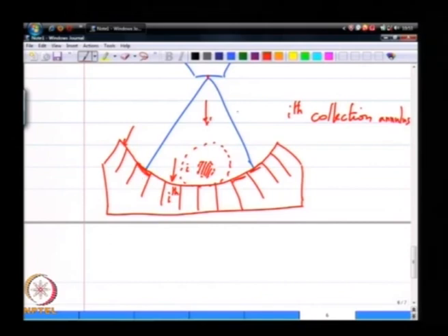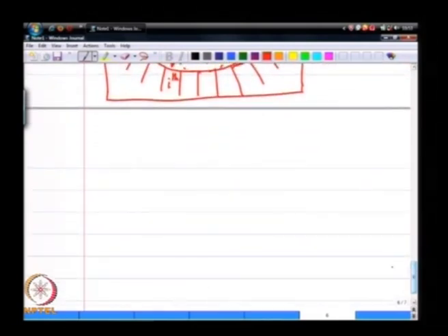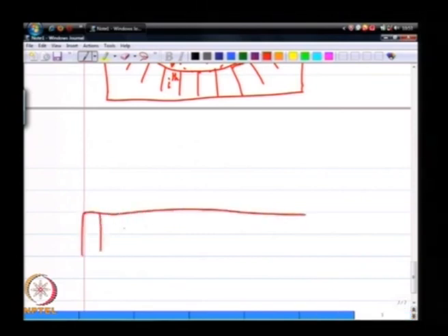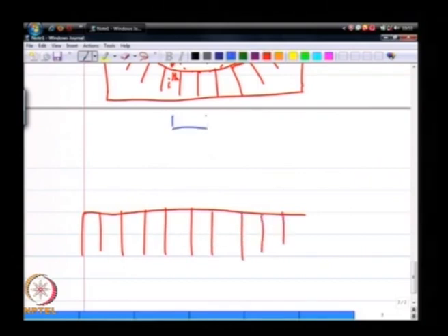So, in an inline design, the v dot dA, the angle between the velocity vector and the area vector are different, and that causes, even though I am thinking that I am exposing the liquid to the same cross sectional area, the cross sectional area that the flow actually sees is different depending on how far out away from the center line that particular sector is located.